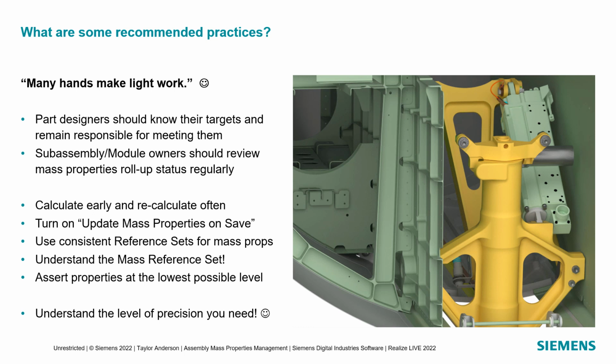That expressions partition is a heavier piece of the part file that's not loaded as part of things like minimal loading. And so minimally loaded assemblies load very quickly, of course, super quickly. And that's great, and you can do a lot of mass property work with assemblies minimally loaded.